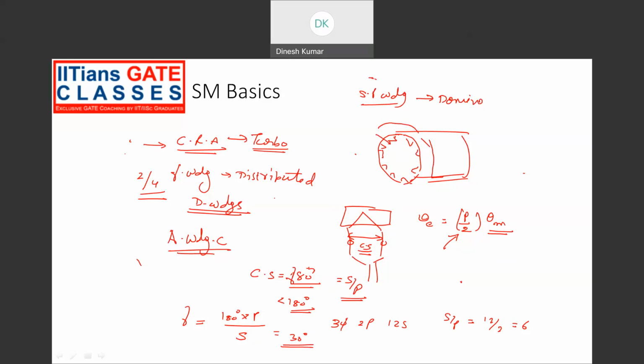So here we are using distributed winding. Generally, distributed winding is used to eliminate higher order harmonics. So in a cylindrical machine, each curve represents a slot, right? As the number of slots increases, the harmonic content in the EMF decreases because the distribution becomes uniform and sinusoidal.